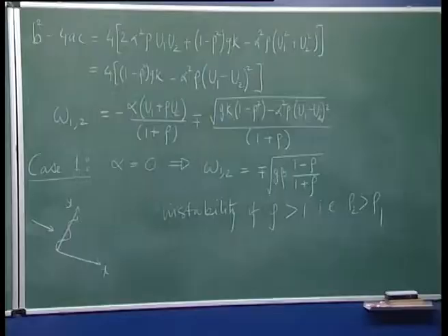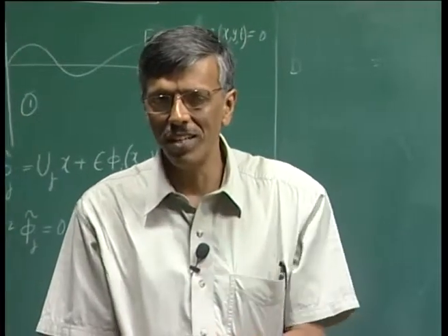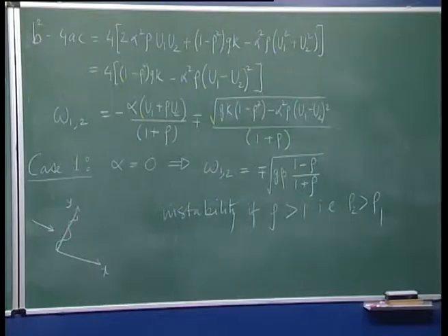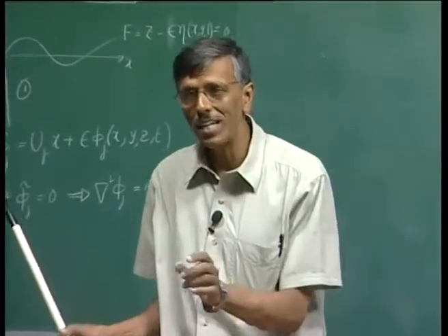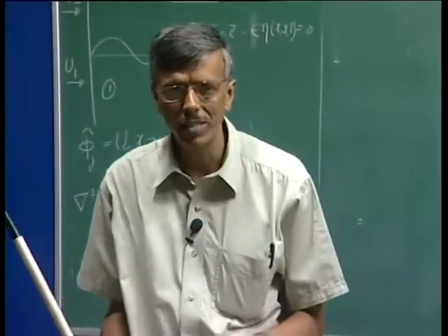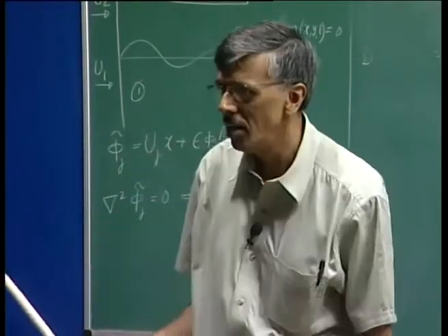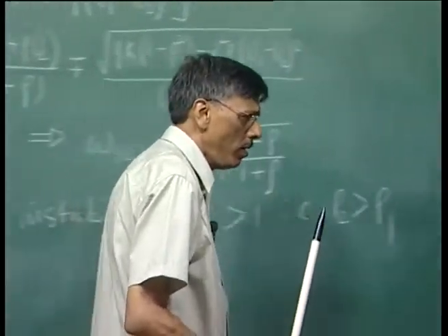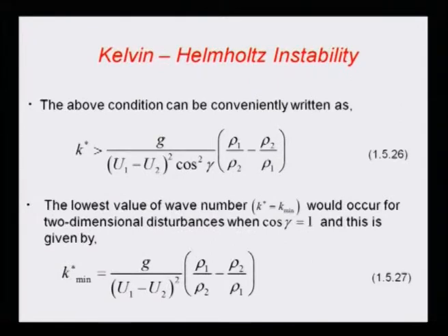So, we have already seen here in the spanwise direction, if we do not have that potentially unstable positioning, then we are going to get a stable condition, right. If I do not put heavier on top of lower, the spanwise disturbance is not going to do anything. And here we are seeing that I am going to get k as minimum. What does it mean? K minimum corresponds to longest wavelength, right. Longest wavelength disturbances are going to be unstable, and that is given by this condition that we have written. So, that is what we are talking about.